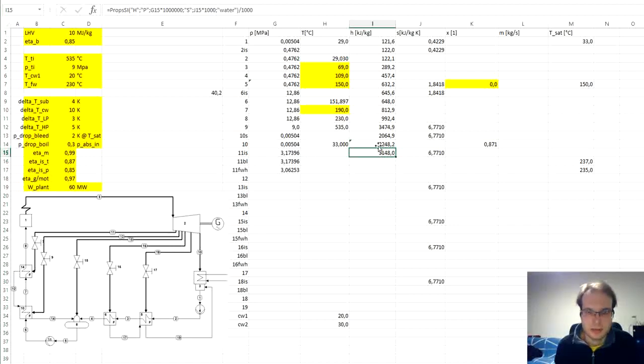So we have enthalpy after the ideal expansion, and now the real expansion is handled the same as the expansion in the entire turbine. We assume constant isentropic efficiency across the turbine. So we can actually use the equation from the point 10, and we will just need to manipulate some variables a bit because the turbine inlet is still 0.9.